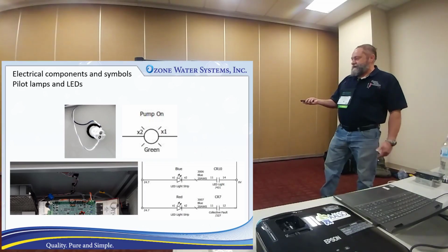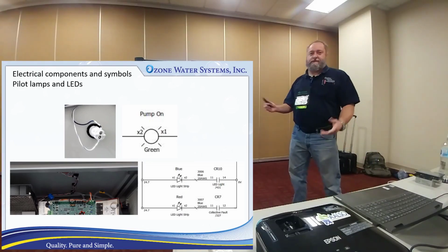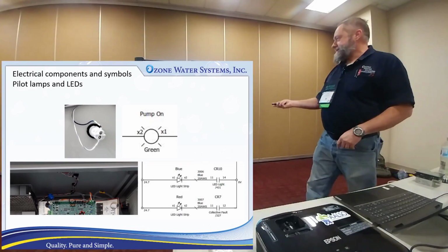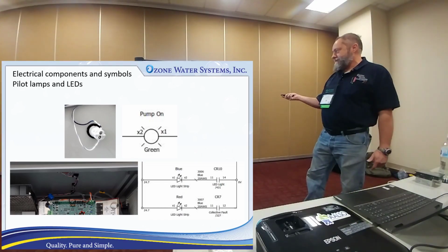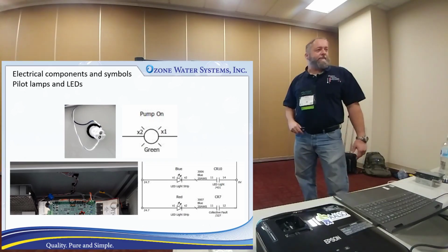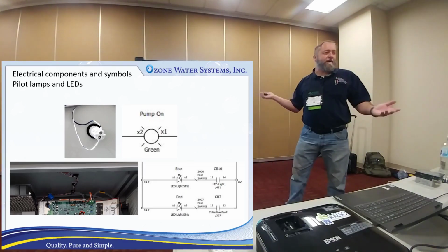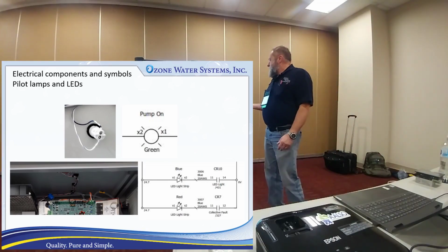So they can be all different voltages, 5 volts, 12 volts, 24 volts, AC or DC, 240 volts, 120, it doesn't matter. It's just to give you an indication that something's on. You're generally not going to need to do any troubleshooting with an LED per se. If it doesn't work, you just won't know that that device is on, but once you verify it, you're not going to have to bypass an LED lamp or something like that.